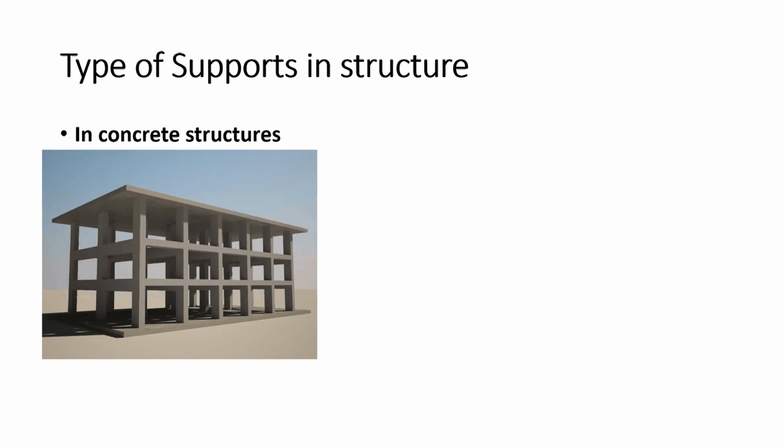Right. So why am I explaining these things with some effort? In real structures, when you are designing structures, based on the connection you provide, you have to understand your functional requirements of the buildings and restrict the movement in the directions and rotation as well, right?